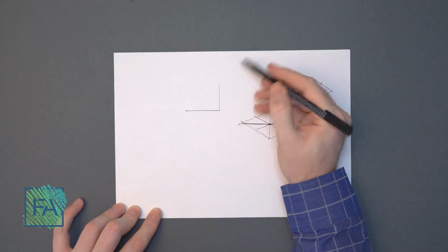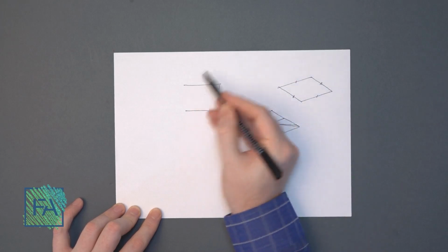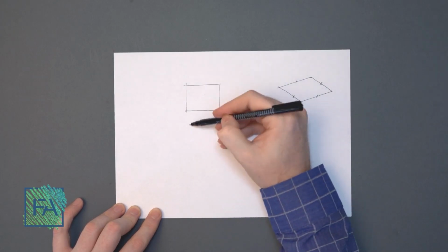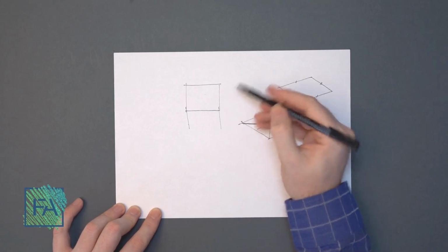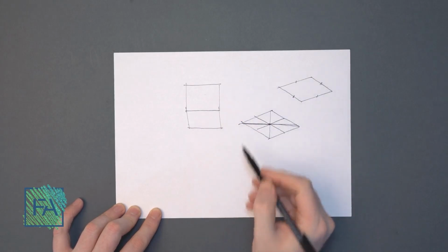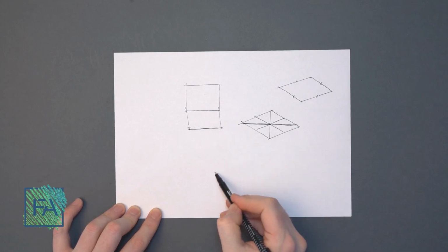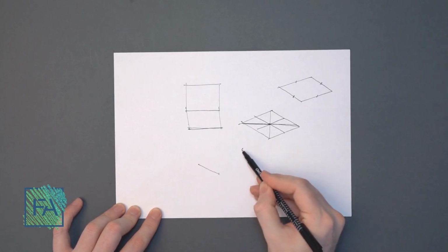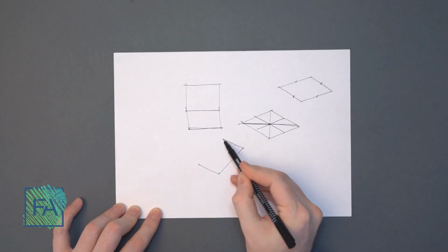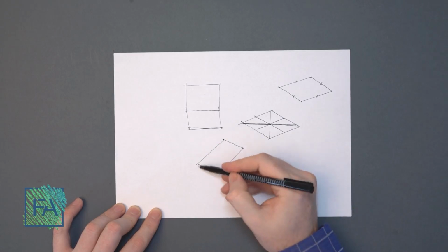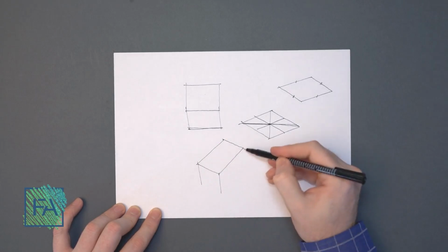So when it's like that, it looks like an oblique object. And this is one technique in perspective as well. We have this, we bring it down vertically and like this. We could use 30-degree and 60-degree angle, which means we have one 30-degree angle and the other one is 60-degree.